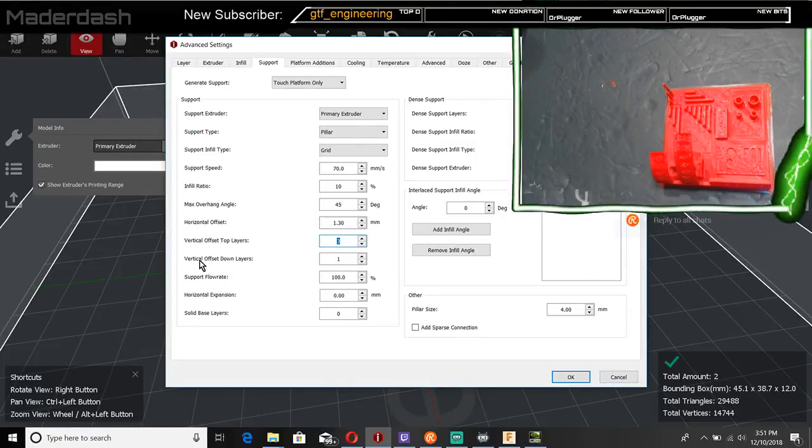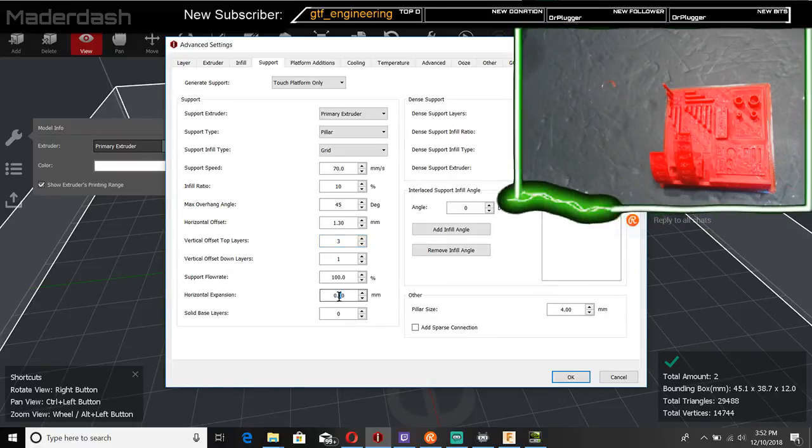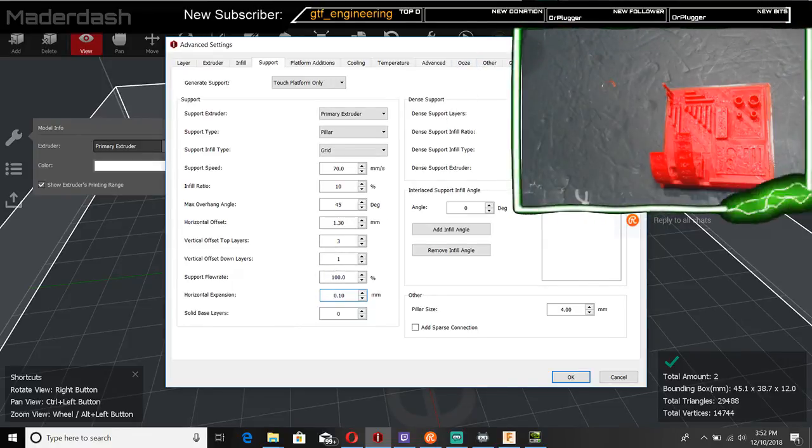Yeah, let's leave that at 3. Vertical offset down layers 1. Support flow rate 100. Horizontal expansion, put that at 10. Dense support layers 1.